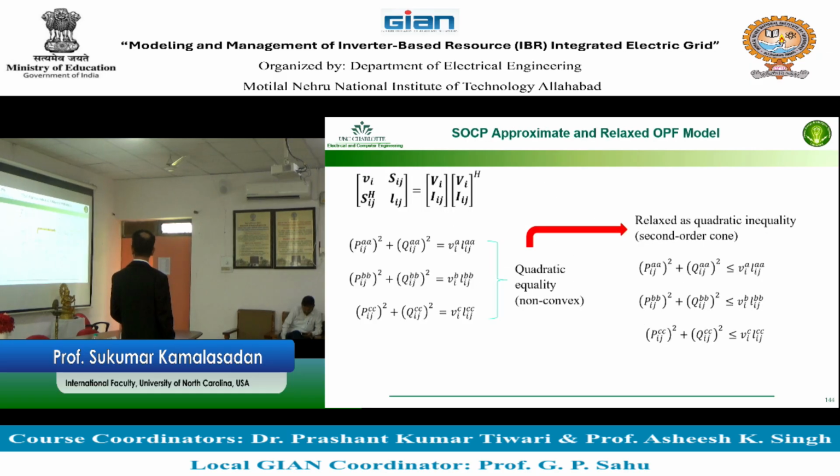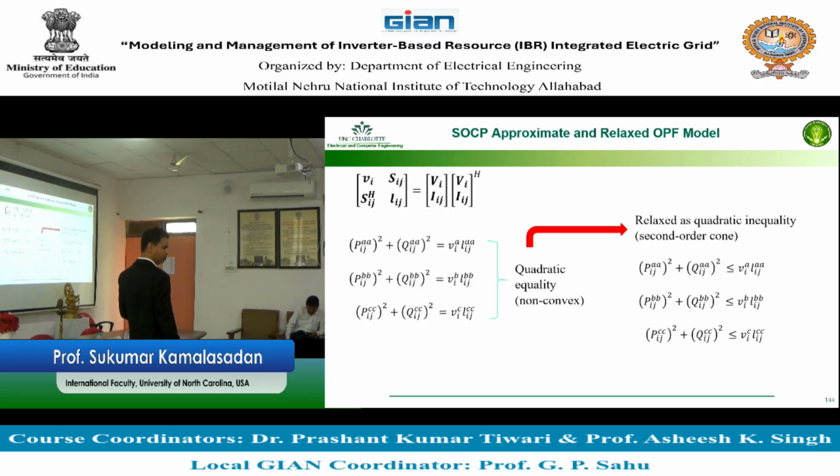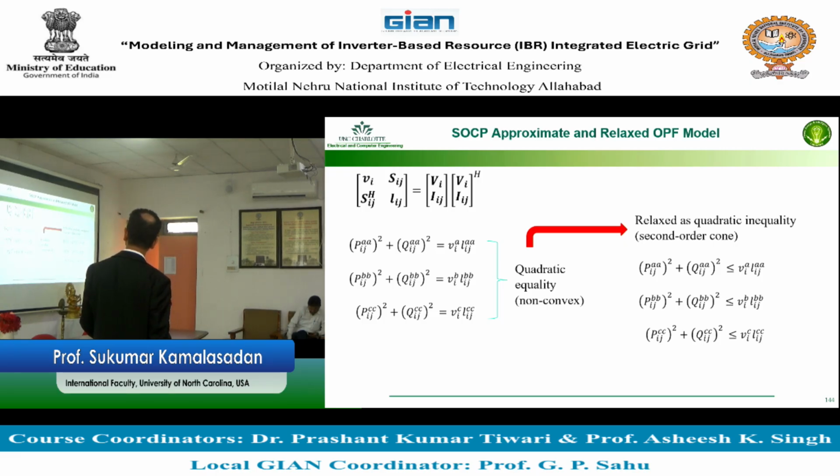If you are going to represent this with second order cone programming, you will cast these power equations like this. This power equation has a very nice feature that is much like a cone. The cone definition comes from a circle at the base. When you have a circle equation, you know x squared plus y squared is equal to c. That's a circle form. But you can relax that as a second order quadratic inequality in the form of a cone.